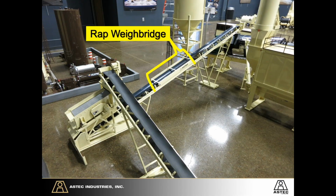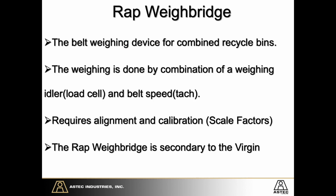As far as the conveying system, you still have a RAP weighbridge. That RAP weighbridge is going to follow the virgin weighbridge. It is the combined weighing for all of the recycle bins. It also has to have the combination of weight and speed. So you've got a weighing idler or a load cell, and you also have a belt speed tach or an encoder. It also requires alignment and calibrations. Sometimes scale factors or constants is what people use for that.